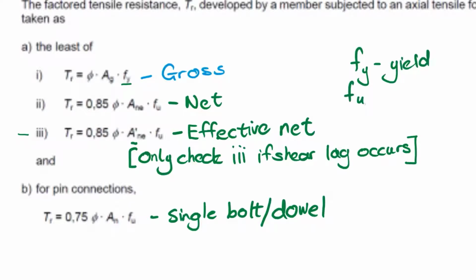And just as a bit of background, looking at how you might get those if you're not familiar with the process, what I've got shown here is actually a test specimen from a test done earlier today in our lab. This is actually on high tensile steel. This was a 550 MPa material, well that's specified, was put in the lab, and then a dog bone was made, so you clamp it each side and then you pull on it and then it elongates and elongates until it fails.